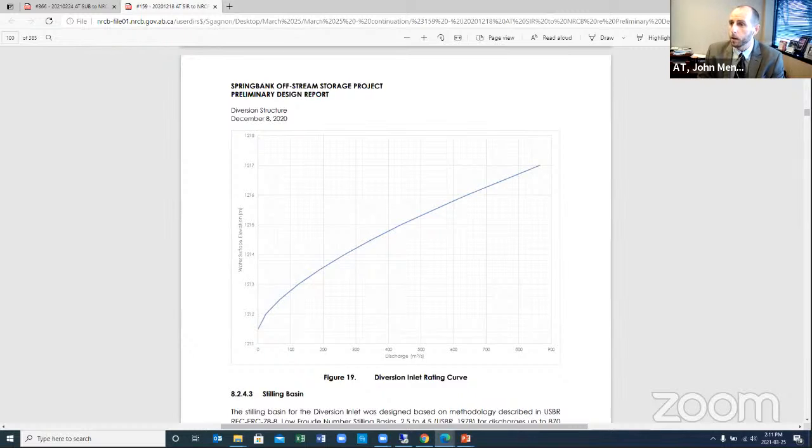In terms of freeboard, when we reference freeboard, what we're worried about is where that water will go and impact. It doesn't impact the bridge. The bridge has been designed for impact loadings from large trees and vehicles. The bridge is not affected by these structures. It's designed to withstand impacts from flows much higher.